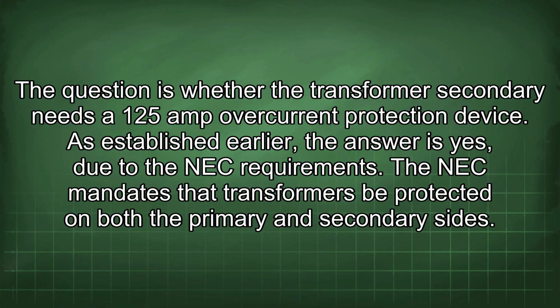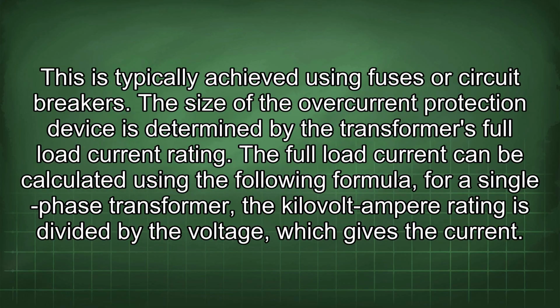As established earlier, the answer is yes, due to the NEC requirements. The NEC mandates that transformers be protected on both the primary and secondary sides. This is typically achieved using fuses or circuit breakers. The size of the overcurrent protection device is determined by the transformer's full load current rating.